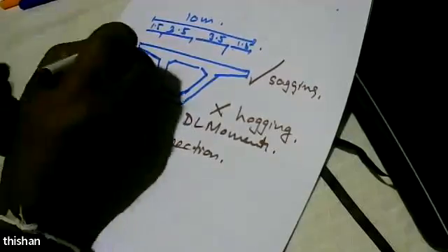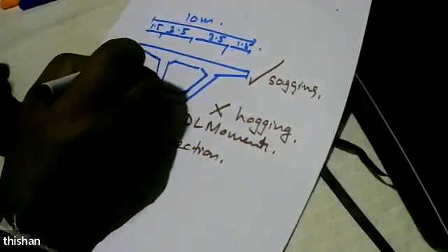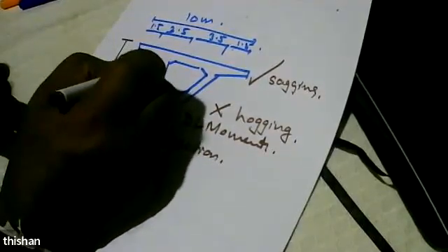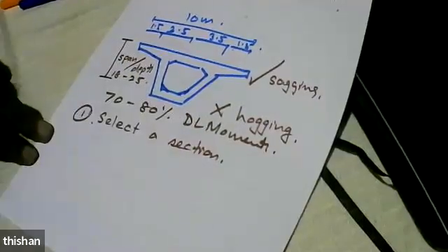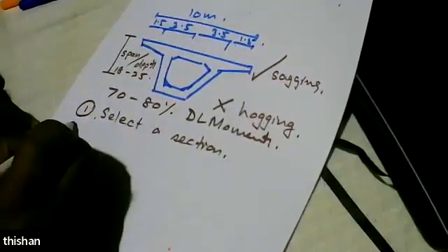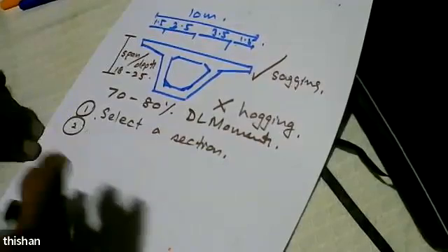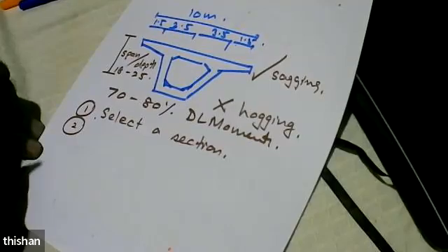And we have to control the deflection. So, span over depth has to be something like 25. You can't have 50. When you look at some of the bridges that have already been completed, you can easily see they have maintained values like 25. Ours will also be in that range.